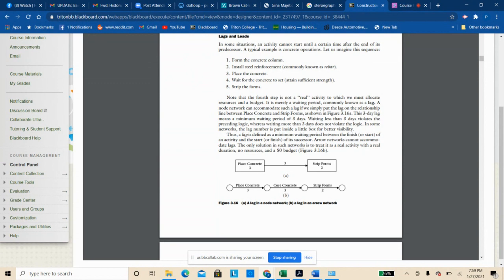They'll actually take cores in specific areas and take that core back to a lab and they crush it. And that test is going to tell them, hey, your concrete didn't cure long enough, or you got a bad mix of concrete, but you're going to have to rip it out because that stuff ain't strong enough.